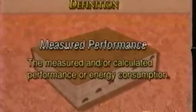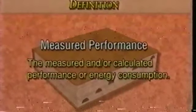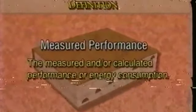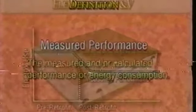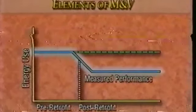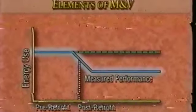Measured performance is the measured and/or calculated performance or energy consumption of the ECMs on energy systems after ECM installation. The measured performance is determined through actual measurements taken at least annually throughout the contract. Measured performance is compared to the baseline to calculate savings and therefore the corresponding performance payment.